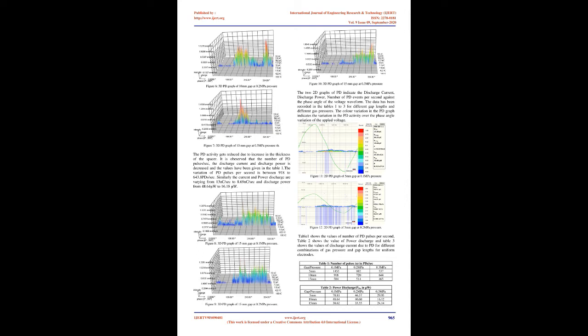RC divider. After calibration, the software is shifted to expert mode and the settings of frequency, charge, and voltage are selected. The voltage is then increased gradually until it reaches a value 20% above the discharge inception level and reduced gradually to 0 to record the extinction voltage.